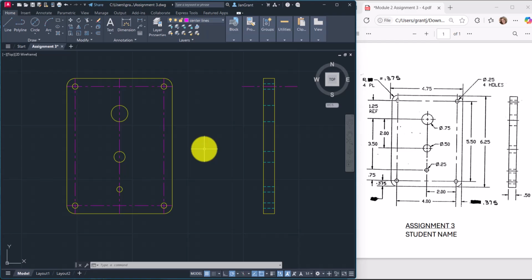I think this is a little too small, so let's go back, LT scale, enter, to 0.75 and enter. I think 0.75 will work, but for us to show that this is a center line, instead of keeping it as a solid line, we'll need to stretch out these lines to show that little dash line right there as a center line. And that works because now it really looks like a center line. So we use the LT scale of 0.75, and we'll put that in our title down here to represent what that is.